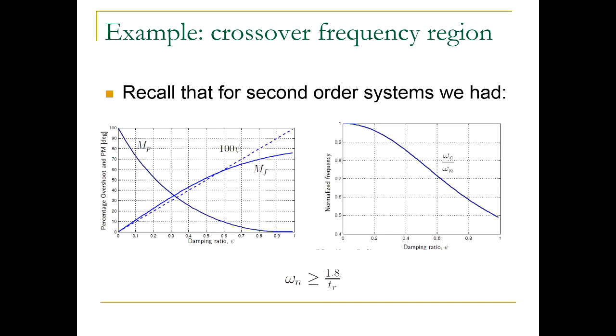Very good, thank you. So it's an approximation of what the phase margin curve does on this range. Maybe from 0 to 0.7 roughly, you would make a small error if you approximate this relationship with just this dashed line. So for all the damping ratios between 0 and 0.67, it's possible to use 100 times the damping ratio as your phase margin. That's just useful as an approximation.